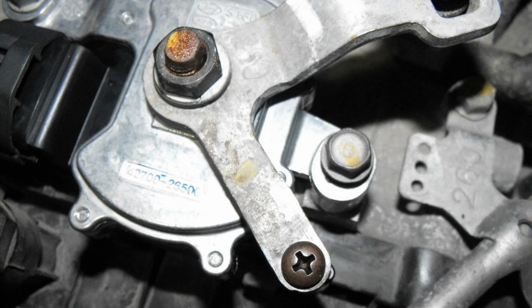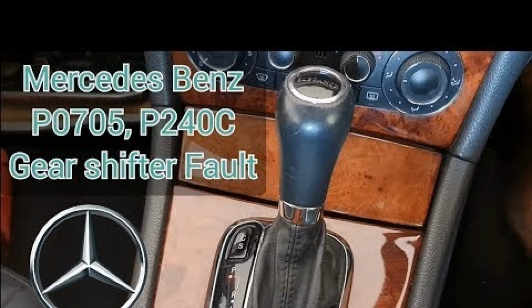Check the sensor if the wiring and sensor tests are complete, but you still receive the P0705 code. You need to check the PCM-TCM module as well as the internal transmission faults. But do this after replacing the TRS sensor. Most of the time, this is the problem. If you're not sure, seek the assistance of a qualified vehicle diagnostic technician.